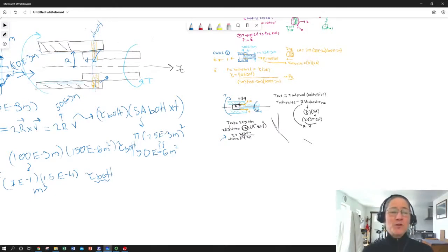We could maybe put a few more bolts in, and so we'd be engaging more cross-sectional areas. So the shear stress in each bolt would be less, and as we put in more and more bolts, eventually we would approach what we have over here with the adhesive, where we're using the whole area. So the more area that you can spread a load out over, the lower the stress, especially in shear, where you have quite a bit of overlapping area available. Unless you have to lightweight it, that's a design option that you might have in mind.